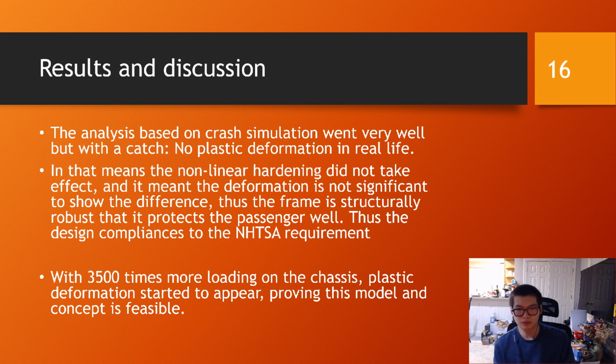But this is a good thing because the frame is structurally robust and it protects the passenger and the car. Thus, the design is compliant with the design requirement from NHTSA. And with around 3,500 times more loading on the chassis, plastic deformation started to appear, proving that the model is feasible and the concept is working.